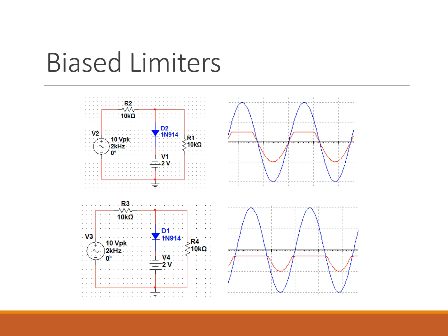So a good design insight would be that if you're looking at the total clipping level, that's going to equal the bias voltage plus or minus the diode drop. Okay. All right, so that's it for this slide. I'll see you in the next one.